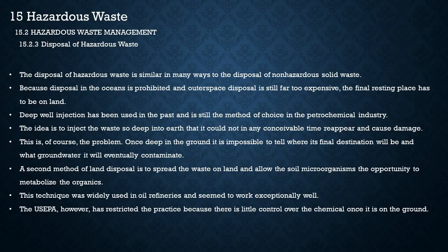15.2.3 Disposal of hazardous waste. The disposal of hazardous waste is similar in many ways to the disposal of non-hazardous solid waste. Because disposal in the oceans is prohibited and outer space disposal is still far too expensive, the final resting place has to be on land. Deep well injection has been used in the past and is still the method of choice in the petrochemical industry. The idea is to inject the waste so deep into earth that it could not in any conceivable time reappear and cause damage. This is, of course, the problem.